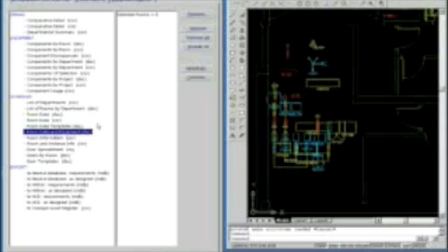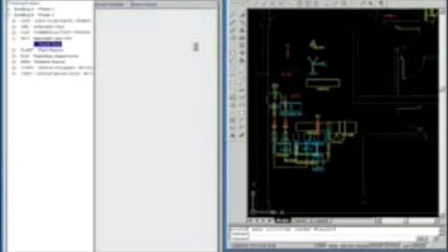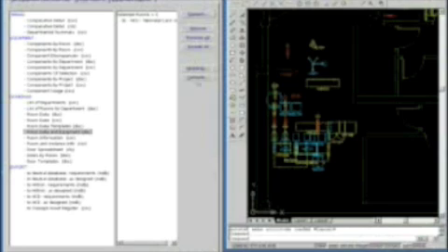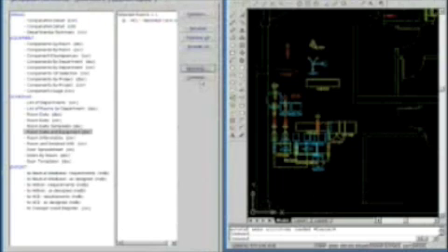I'll produce a room data and equipment report for the treatment room. I bring up Explorer, drag and drop the room or rooms that I wish to report on into the build list, and select the headings button. The headings button allows me to format the header of this Word document, for example, in terms of company name, address, telephone number, and so on. The more important button is the contents button.